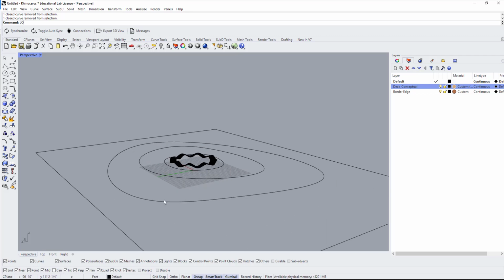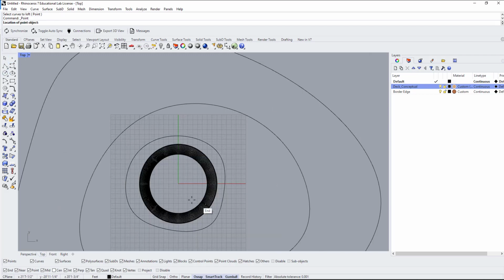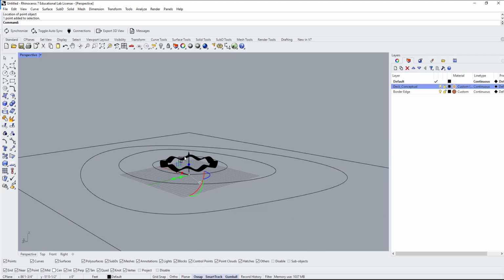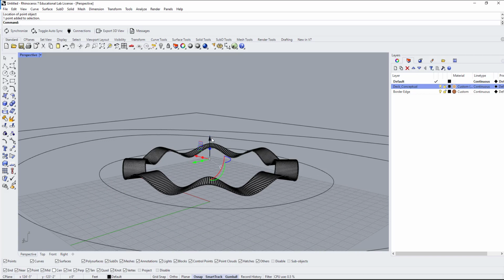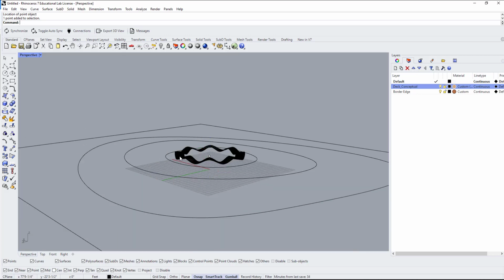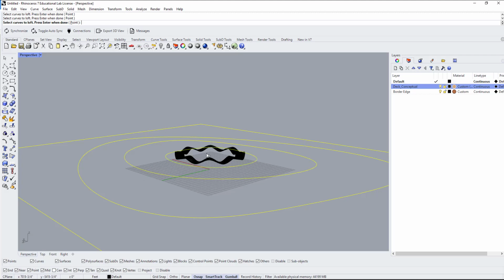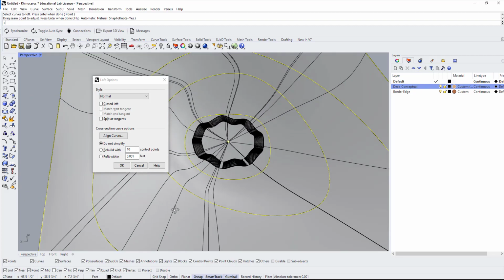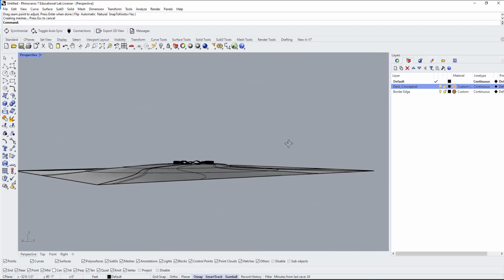And now that we have everything, one of the ways that you could create a nice closed contoured site is to loft your lines with a point. So I have created that point and I'm moving that up. That's exactly 20 feet. I made a small mistake, so that would be 15 feet, I think. So now I'm lofting all the curves and that central point. And if I'm happy with the result, I'll just hit OK. Now we have the site.